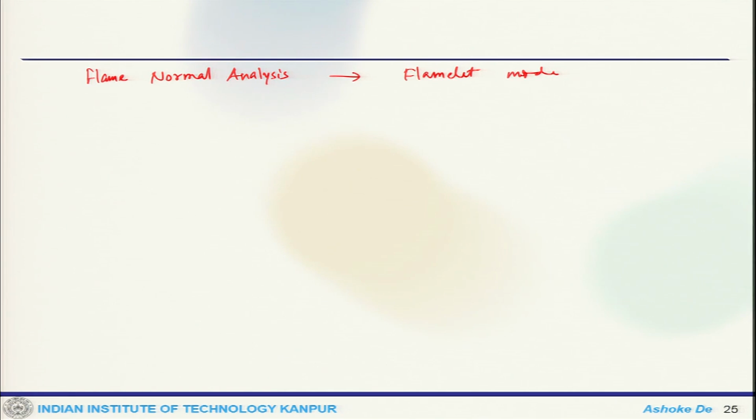So, the probability density function of the independent variable C or Z is used. If you use one-point analysis, that will lead to PDF kind of methods, where the equations of the probability density function fluctuation at one point are modeled and solved.